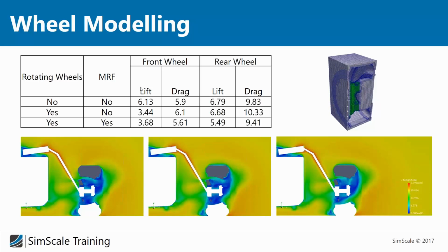For sure, using a dynamic mesh where the parts are really rotating is maybe more accurate, but again, for a full car this is so complex that usually it doesn't make sense to do it, because the gain of accuracy compared to the effort is much smaller.